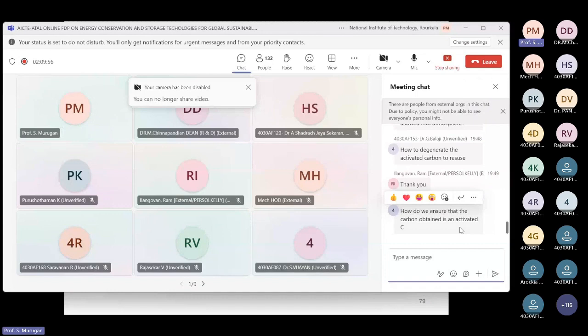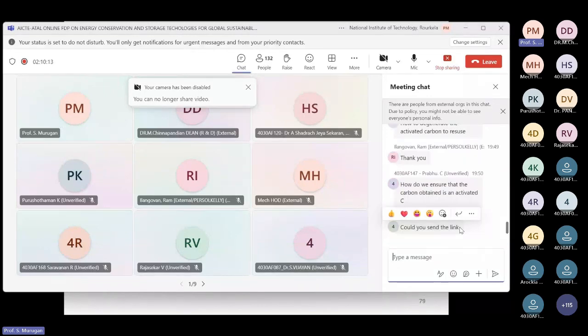Normally, for regeneration, they remove the particulate trap and either manually clean it by burning the carbon soot, or continuously apply compressed air. If you forcibly send compressed air, then that carbon soot will fly.